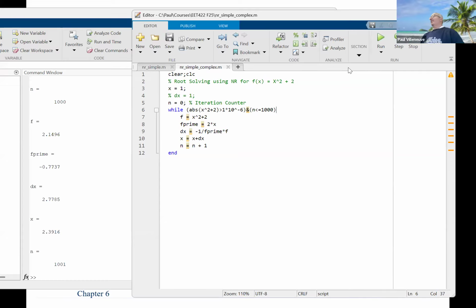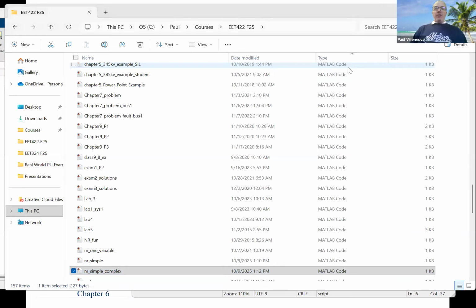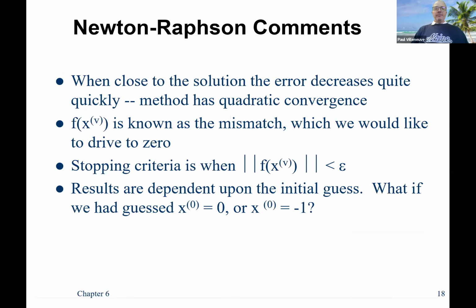Just won't get there. So why does that complicate things for us? Because when we talk about power systems, we have P plus jQ. We have a real part and an imaginary part for our impedances. So when we start writing our equations, we have to start stripping out the real parts and the imaginary parts and isolating them into separate equations so that all the numbers are real, but then we'll just have to keep track: is this real or is this reactive? And go from there. We'll actually do magnitudes and angles to make it work, but you'll see how that works once we get into that.